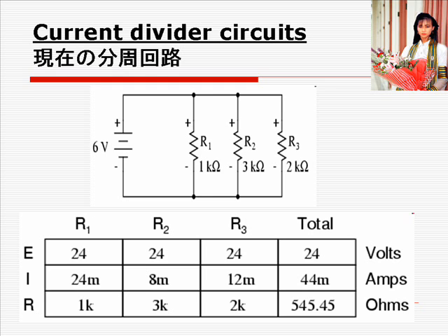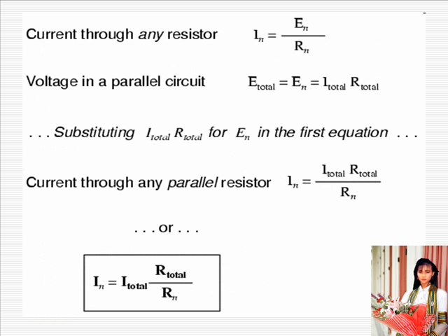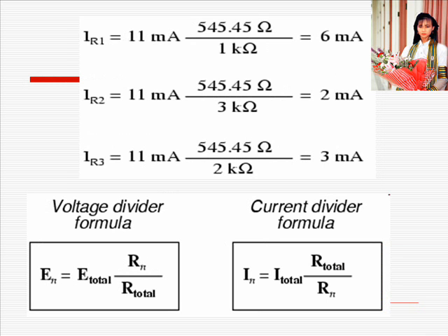The current through R1 is still exactly twice that of R3, despite the fact that the source voltage has changed. The proportionality between different branch currents is strictly a function of resistance. Also reminiscent of voltage dividers is the fact that branch currents are fixed proportions of the total current, despite the fourfold increase in supply voltage. The ratio between any branch current and the total current remains unchanged.